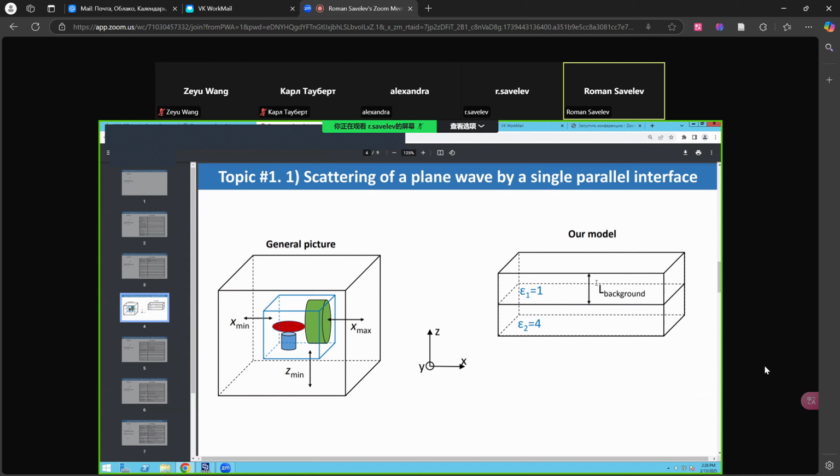When you have near fields, and you put a port or PML boundary conditions very close to the object, these near fields can get absorbed by the PML or scattering boundaries.